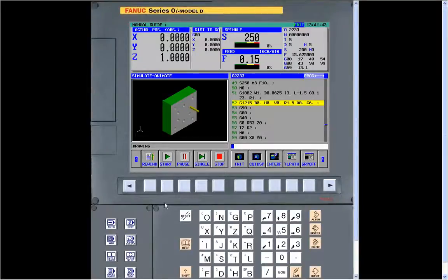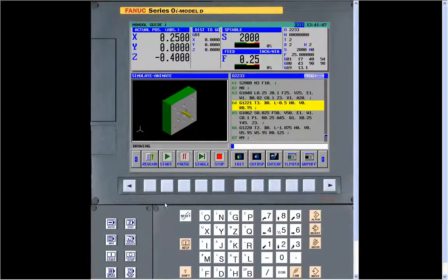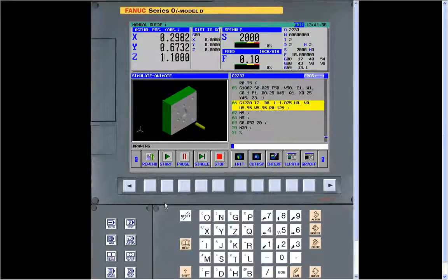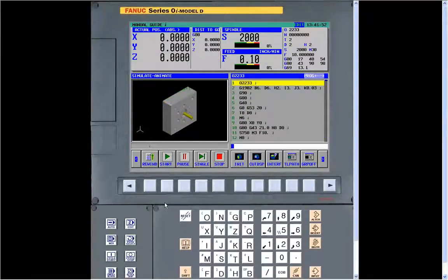Okay. There, it's tapping the holes. Now it's doing the pocket in the middle. Okay. And it does the outside. And there it's done. And then if we go right shift from there, we have a soft key that says insert. And it says machine time data is inserted. Okay. Yes. See, it puts time.